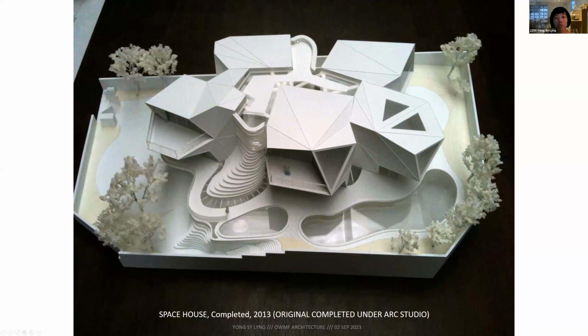Now I show you the rest. Basically all the freeform curves are very difficult. When the contractor first started this project, they even had problems plotting out this curve on site, right? How do you make sure that you are accurate on site, and how do I mark up all these things? In the end, we found a method using rebar. So you bend rebar and then mark points, right? Eventually they built the pool first. So after learning how to build two freeform curves, they can then handle this staircase, right?